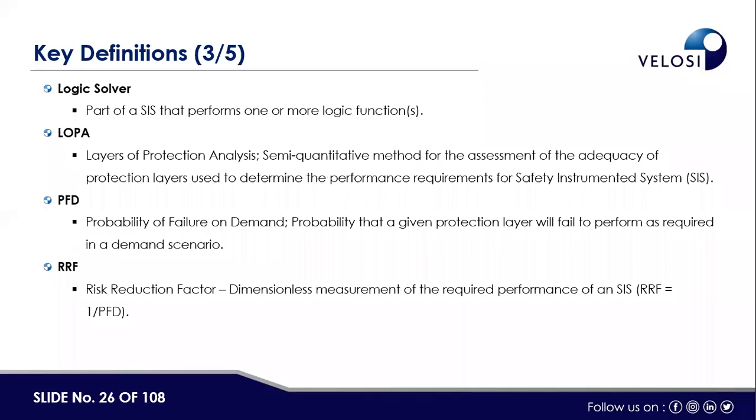Logic solver means basically the controllers, and in process plants normally PLC, DCS, SCADA system or ESD system are called logic solvers. LOPA is layer of protection analysis, which we normally use for SIL analysis. This is one of the techniques of SIL analysis. And SIL means safety integrity level. I will be covering this next part.